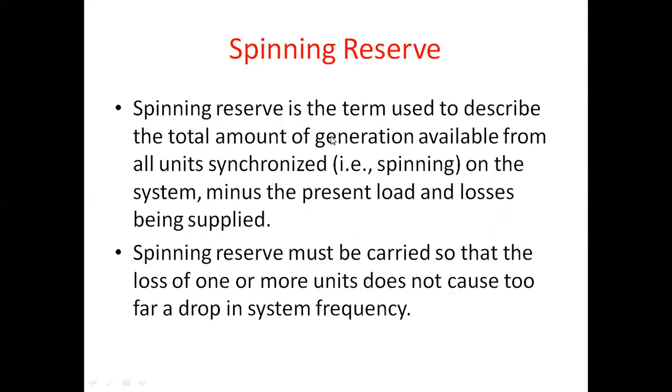One of the important factors is the spinning reserve. What does that term mean? Spinning reserve is the term used to describe the total amount of generation available from all units synchronized, that is spinning, minus the present load and the losses being supplied.